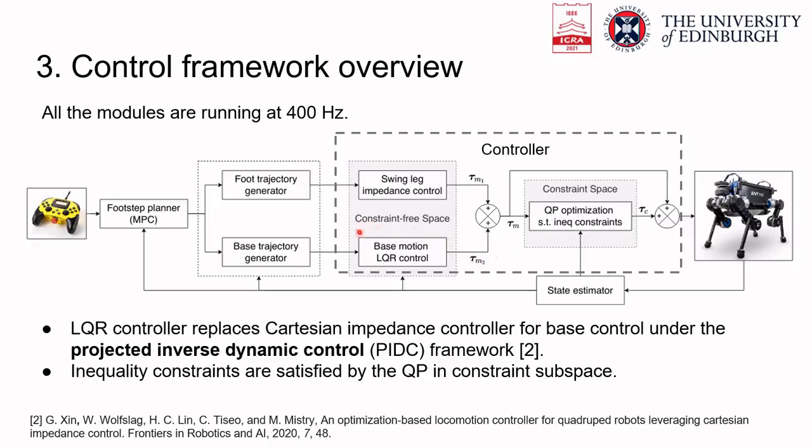In this paper, we replace the impedance control for the base with the LQR controller. The LQR will generate better feedback gains than manually tuned diagonal gain matrices.